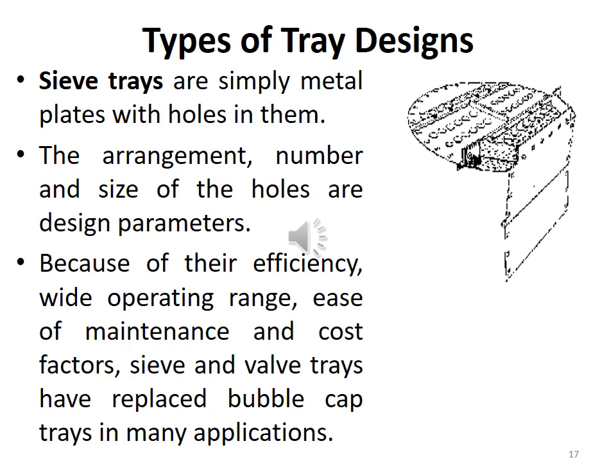The vapors lift the cap, and this is a self-creating flow area. After passing vapor, the caps direct the vapors to flow horizontally into the liquid, providing a better opportunity of mixing vapors with the liquid.